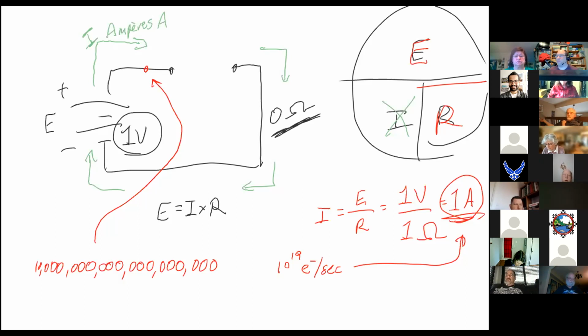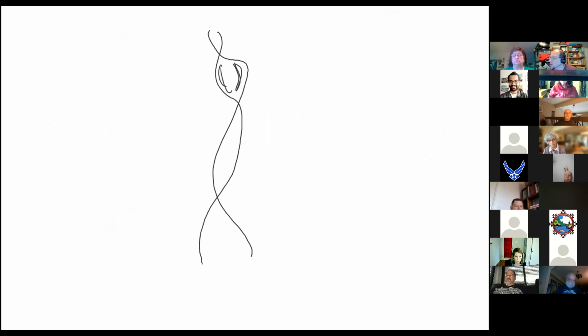Yeah, aluminum is also a very reactive metal and it oxidizes very fast and it forms a black layer on the surface. And that black layer is not conductive. So the center of the aluminum is conductive, but the surface is not. And what happens is if you try to put two pieces of aluminum wire together and you twist them together, wherever they're not immediately touching, you'll get a layer of oxidation that forms, which is not conductive. And then you'll have a high resistance forming. And this is where we get to our next part of it.